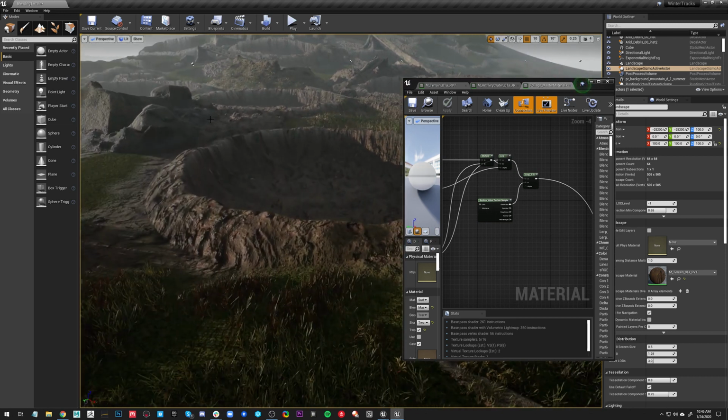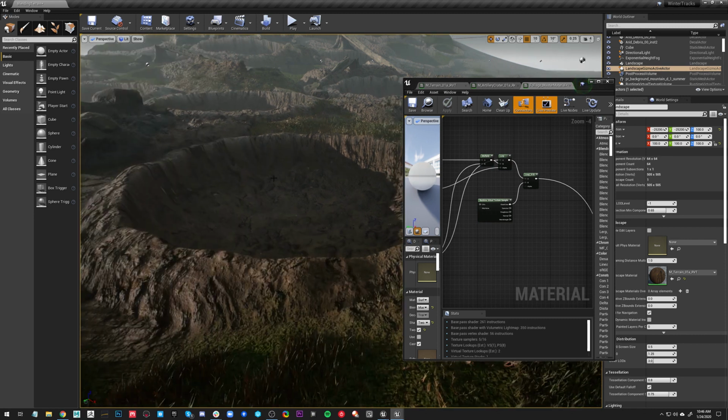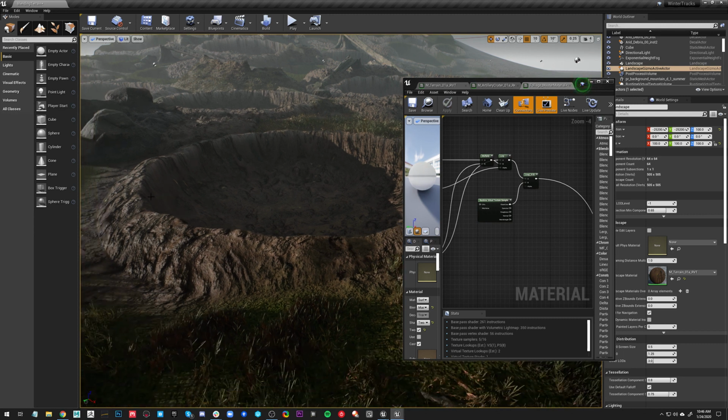generally, if I wanted to get rid of that, I would have really rounded out this edge a lot in order to avoid this kind of stretching. I think of another option you could do: I suppose you could blend between different techniques. If you wanted to do world-aligned texturing just along this edge and then have the rest be based on UVs, you could use vertex coloring to blend between the different options.